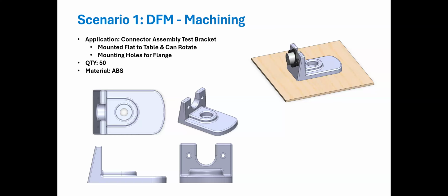So besides fillets, there are a couple more things that may make this part more costly. Those counterbores are really deep and out of position, so you couldn't fixture your part well to get to them. And are they functional? Perfect, that is a great observation. The counterbores are not necessary.